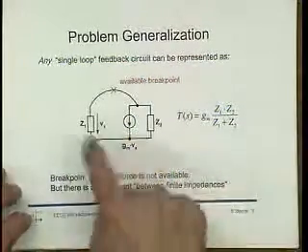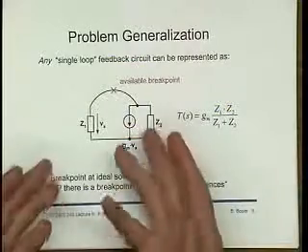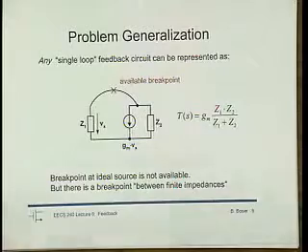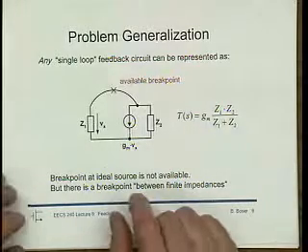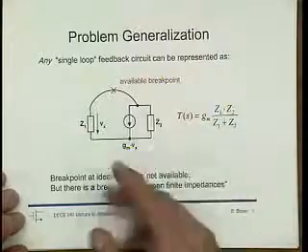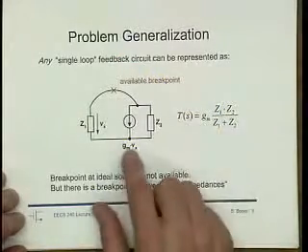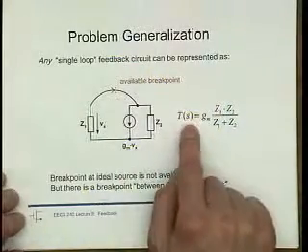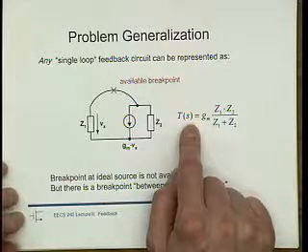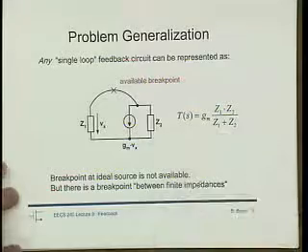But then, of course, we can calculate for this circuit using completely normal nodal analysis. By breaking the feedback loop here and using the return ratio trick that we looked at last time, we can figure out what T of S is. T of S depends on that gain and on these impedances.